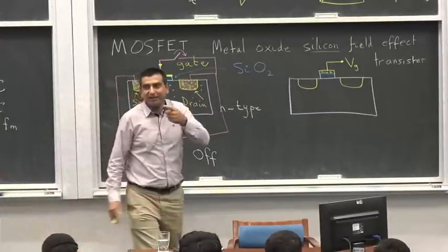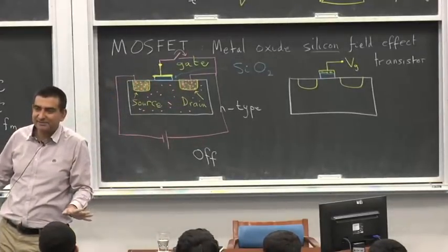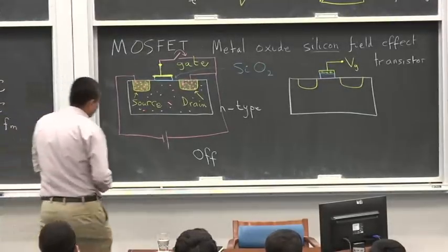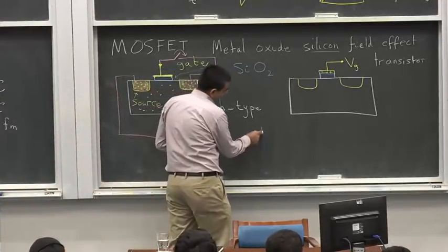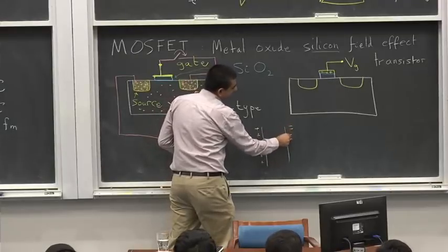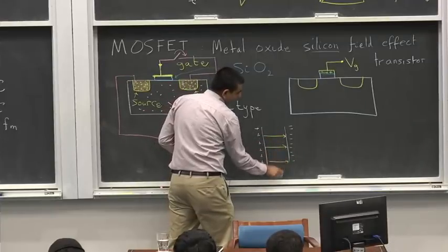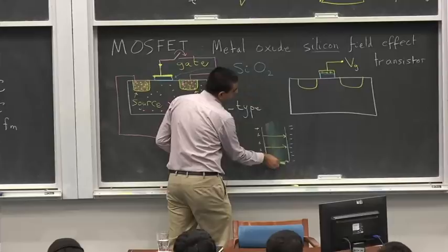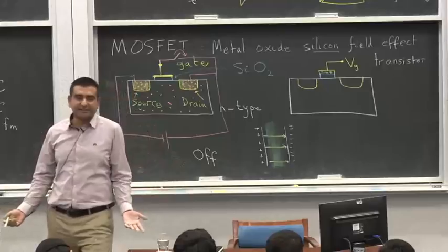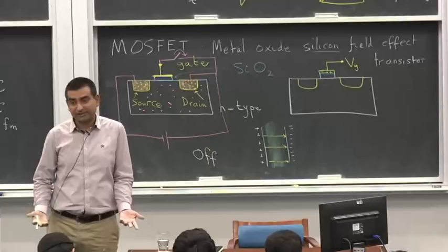So are you surprised with this fact, or is it common sense? You can have an electric field inside an insulator as well. Just remember a capacitor. If you have a positively charged plate and a negatively charged plate, you can have an electric field inside, and here you can have an insulating material. You can have paper, mica, air. The electric field can exist, but charges cannot flow. Currents don't exist.